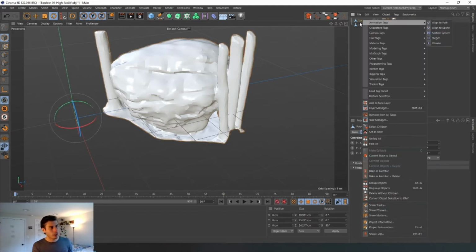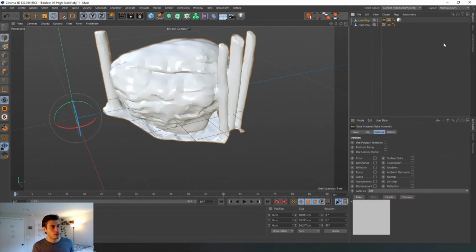And then I'm going to right click on my model and go into bake material. What we're trying to do here is create an ambient occlusion map so we can figure out where those points on our texture that are already too dark need to be lightened up. And we'll do that in Photoshop or in some photo editing software.